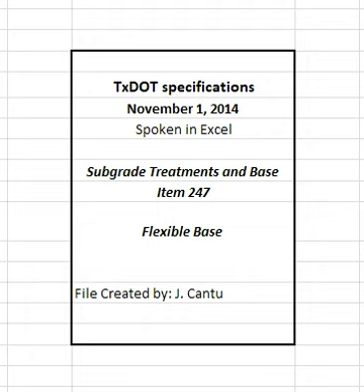2.1.2.2 Type B crushed or uncrushed gravel. Blending of 2 or more sources is allowed. 2.1.2.3 Type C crushed gravel with a minimum of 60% of the particles retained on a number 4 sieve with 2 or more crushed faces as determined by TEX 460A, Part I. Blending of 2 or more sources is allowed.